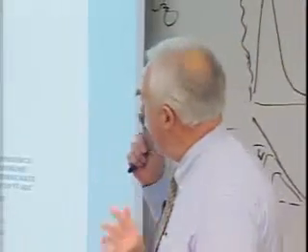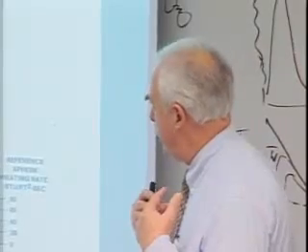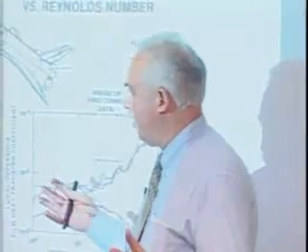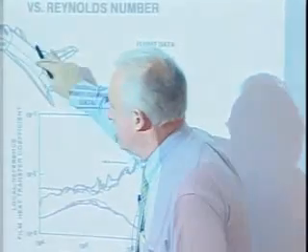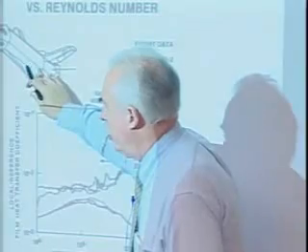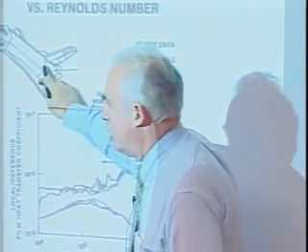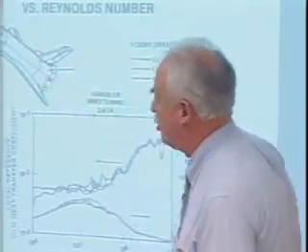By the way, Aaron, Max Fouché told me to burn a hole someplace on the lee side. He didn't want too much tile there. The only thing I was able to do was we exceeded heating here because we didn't simulate the flow very well in a wind tunnel. We had to put tiles there after first flight. So I told him that was as close as we came.